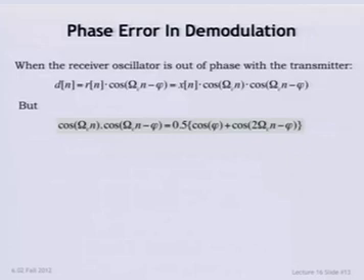So that's really what this is trying to do. We're saying d[n] is your received signal, but the local oscillator or the local cosine that you're heterodyning with at the receiver doesn't know exactly what phase was used at the transmitter, so you've got to assume that there is going to be some offset. So this is actually what the multiplication is. And now you use a simple trig identity. It's the cosine of something times the cosine of something. That splits into this. And so what we're actually going to get from the heterodyning at the receiver is x[n] times all of this. Okay?